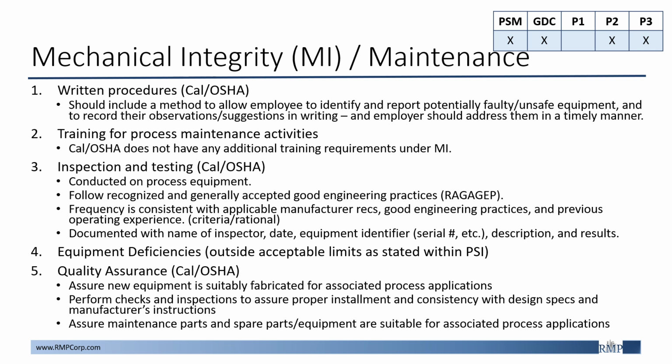Another one is that you have no plan for replacing equipment when it fails, no program for monitoring integrity of tanks, notably the worst case vessel that we're talking about, and failure to consider piping, particularly underground piping failures and maintenance for the piping.